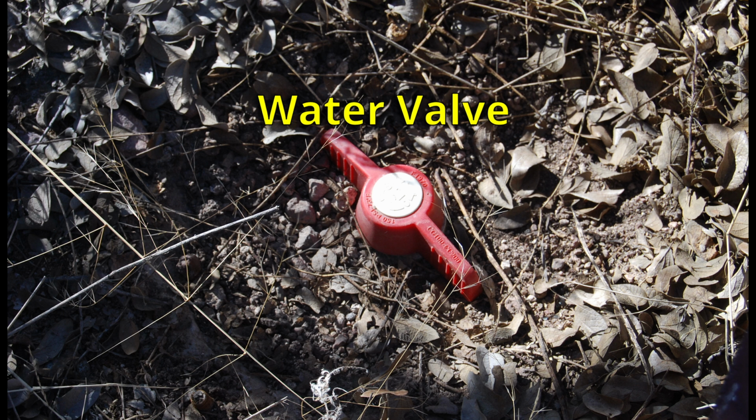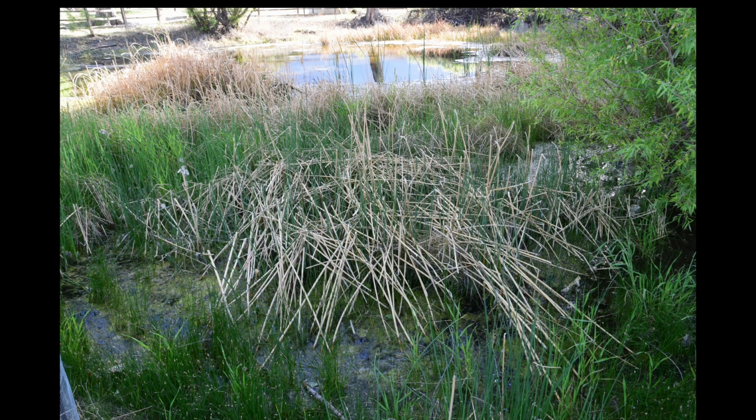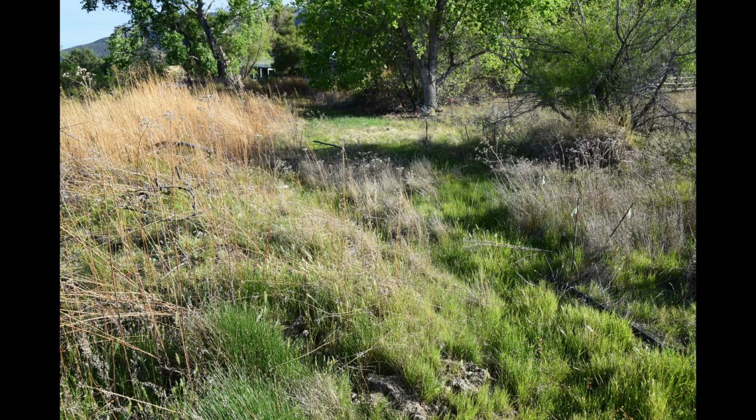A pipe carries the water from the spring high in the mountains to the Brown Canyon Ranch Pond in the valley. Because there is almost always water flowing out of the Brown Canyon Ranch Pond downhill into the Wild Duck Pond, we built a spillway that was 12 foot wide and level in cross-section to handle the overflow from one wetland into the other wetland. The spillway from the Brown Canyon Ranch Pond carries water over a gradual 1% slope into the Wild Duck Pond.